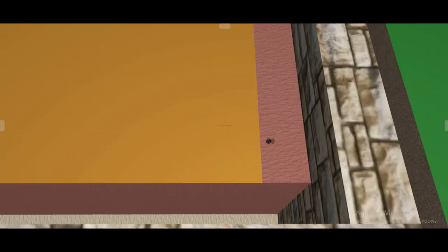And because this width now of this backfilling is 200 millimeters, I simply write it in the description column. But if I want to cube the whole thing now, I turn this 200 millimeters into meters, that is 0.2 meters, and then I multiply by the mean gap, that is 37.60, by this depth now, that is 0.85. So when I keep everything, it is that value that I now carry on to the Bills of Quantities.